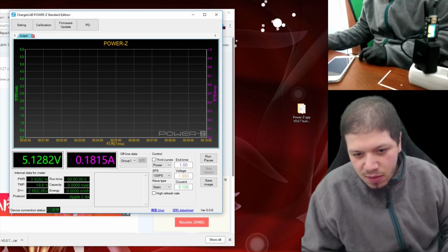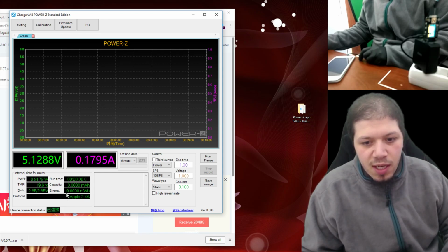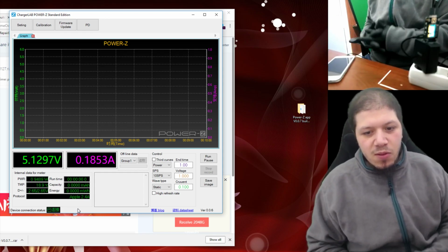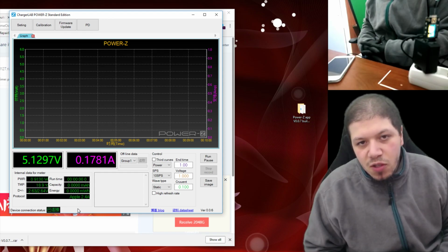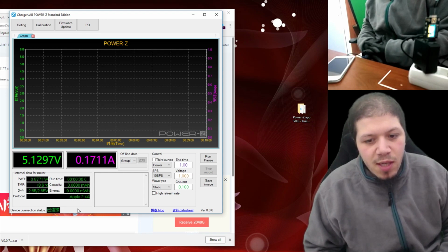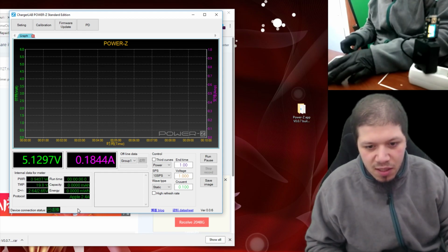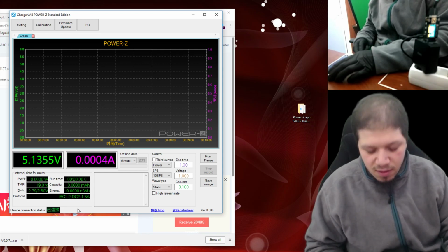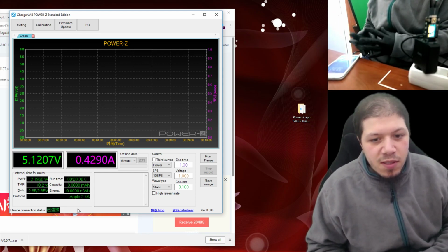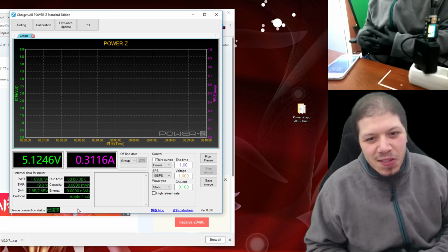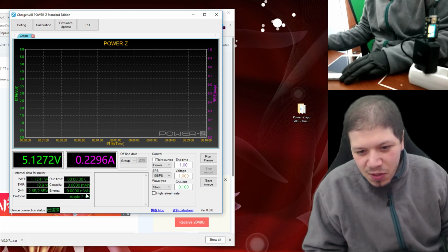And nice thing about this is also it will show you the charging protocol. It shows you here Apple 2.4 amps, and I use this one quite a lot for example TriStar issues. What I noticed is whenever TriStar is defect, it will not show the Apple 2.4 A protocol, but some errors and other kind of protocols like this one. Yeah, and that before I even open up the phone, it almost gives me a certain direction that yeah, TriStar is defect and let's go replace TriStar. So that's pretty nice feature that it will show you the protocol.